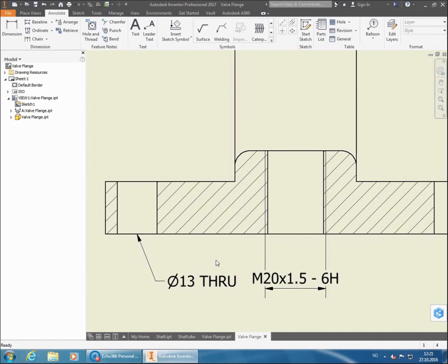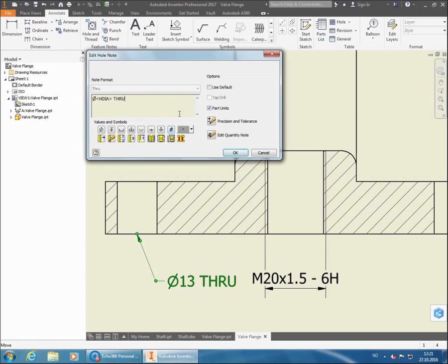With the clearance hole, it is possible to add extra information. Since we've used the clearance hole function when we created the 3D model, we can start adding information in here. We might want to know what kind of bolt is going to go through here, the fastener type, so we can put that in. We might want to know the size of the fastener. And we might also want to know the fit value, if it's a close or a normal or loose fitting.